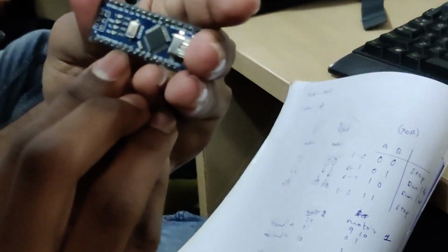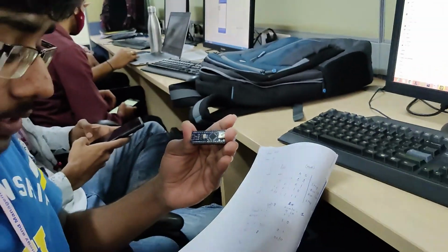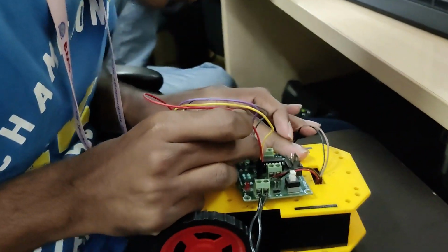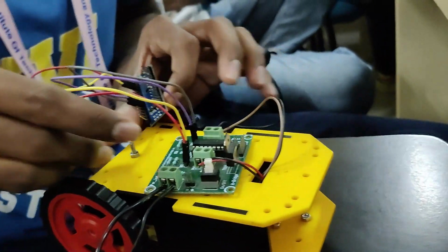Now we have imported libraries like Firmata for the microcontroller, Firebase DB for retrieving the data from Firebase to our PC. So we will be sending the output signals to our microcontroller. We will be using D3 and D4 for the left motor and D9 and D10 for the right motor, and this completely depends on you which pins you want to choose. But they must be digital pins.